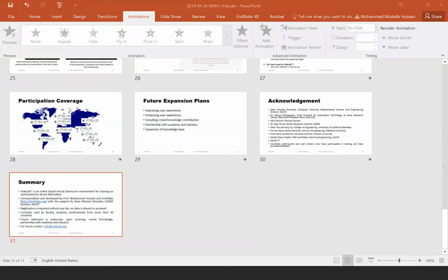Centurus or Athena, like most of these TCAD tools, let us set process parameters and design a device and see how the device characteristics and performance will be impacted by different process inputs. It can depend on the different models which already exist within the library, right?